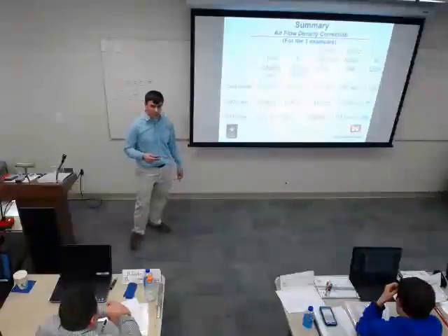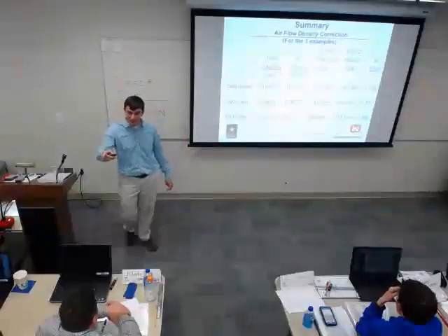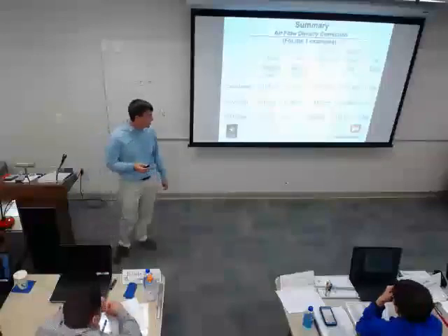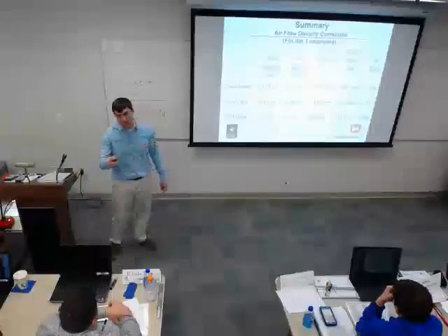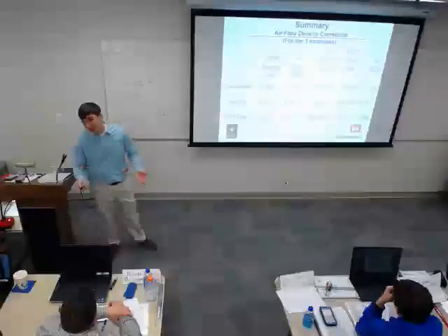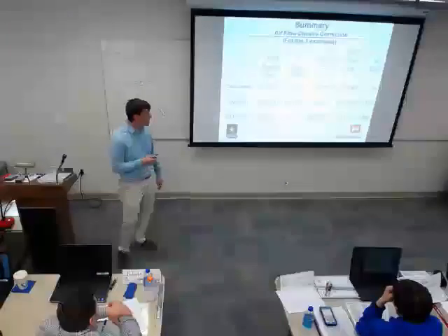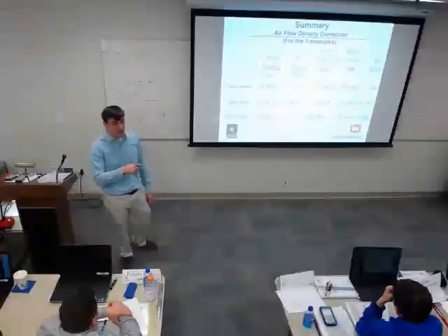Do we have anybody here that's above 2,000 feet? Yeah, project of 14. Most of the instruments are probably going to correct for it, but it might be a question you want to ask. Might want to find out. If you're ever in those locations, I'd be asking my TAB guy to make sure his instrumentation is corrected for it.